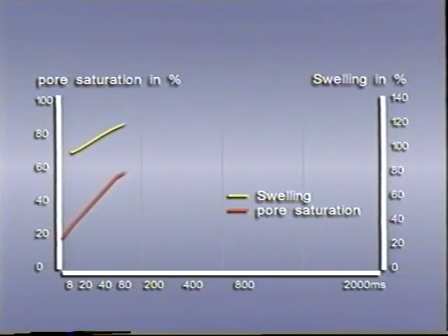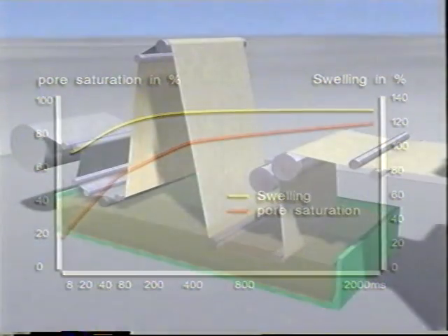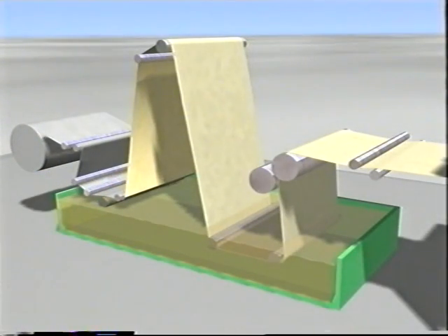After 100 milliseconds, the resin reaches the other surface, and after 400 milliseconds, the pores are approximately 80% full. After 2000 milliseconds, virtually all of the pores are saturated, although a small portion of pores remains vacuous. An additional surface coverage occurs during the following dip, but this resin does not penetrate into the paper.